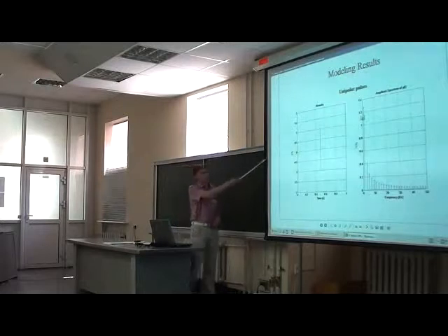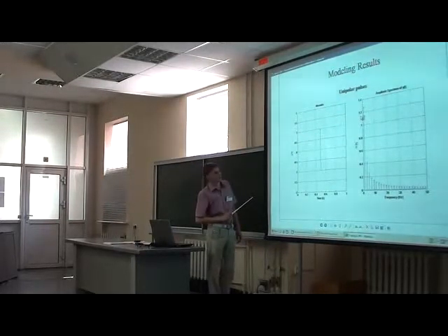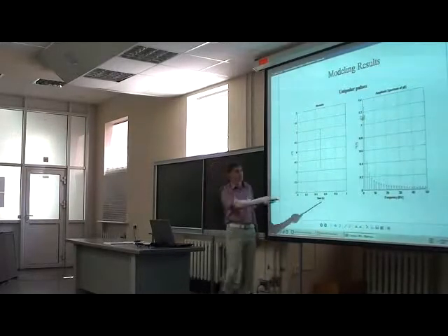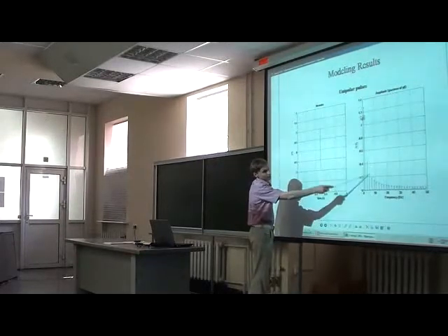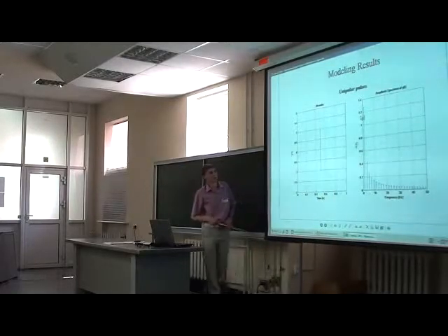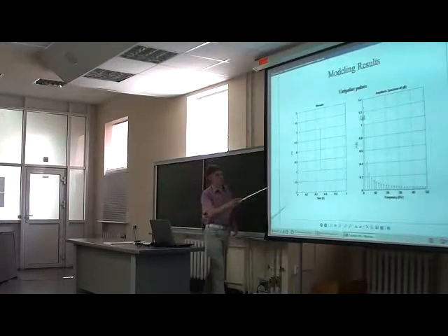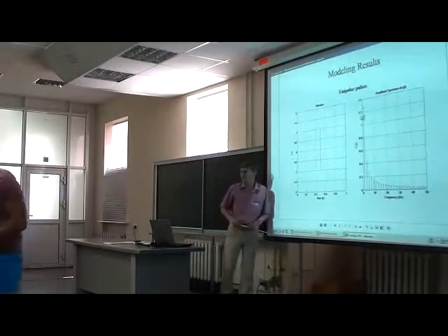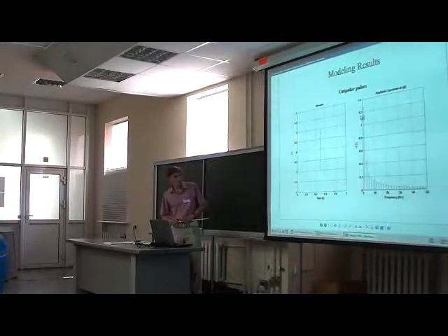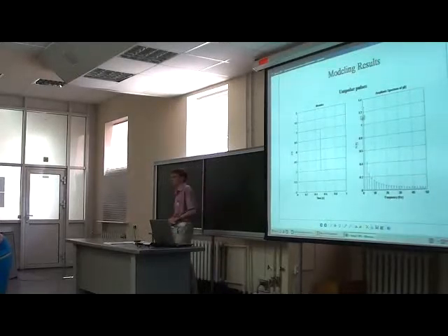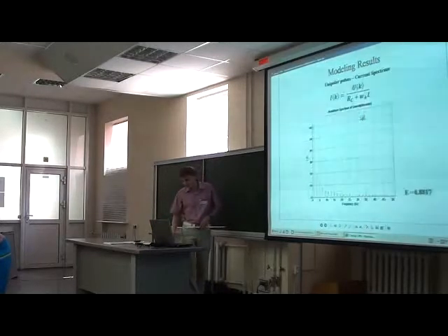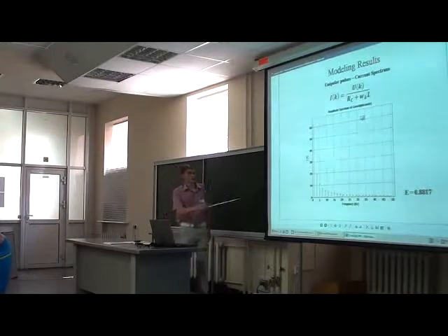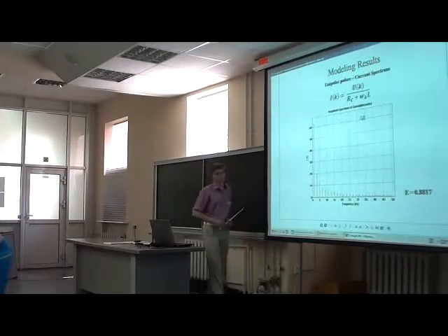So the first one, unipolar pulses. Here is the time domain, here is the frequency domain. You can clearly see here the third and fifth harmonics of voltage. These harmonics have a very negative influence on the motor, because at these frequencies the motor gets low oscillation of the rotor and heat evolution in the windings of the motor. Here we get the current frequencies.